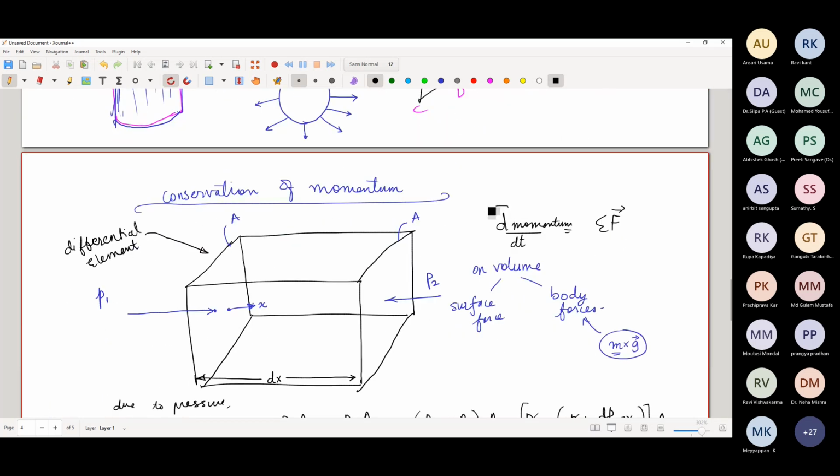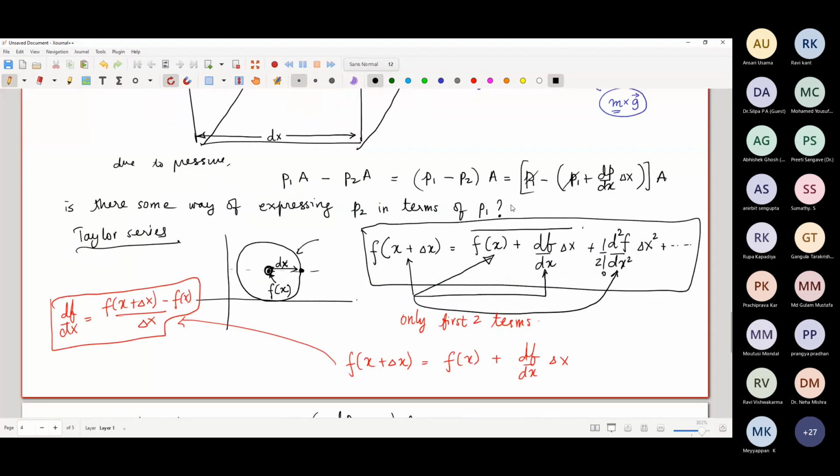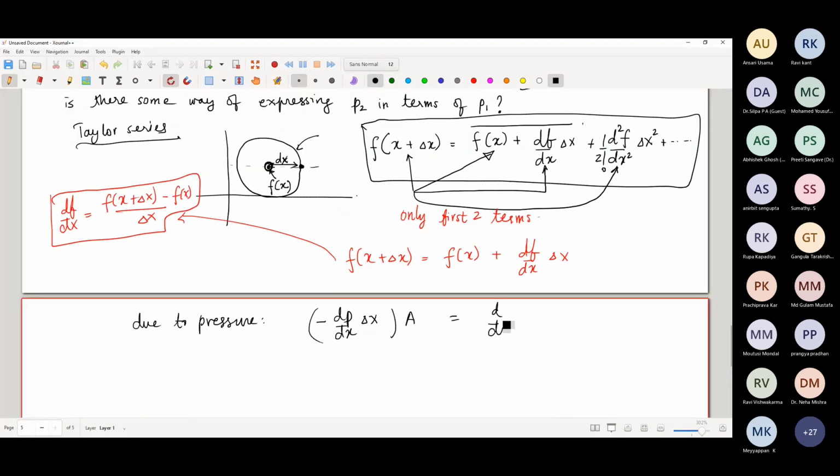if I write down that the rate of change of momentum is this, then this will be d dt of mass times the velocity in the u direction, because the momentum has three components, because it's basically mass times the velocity, and velocity has three components. So the x component of velocity is called u, the y component of velocity is called v, and the z component of velocity is called w. This is classic notation that is used throughout fluid mechanics.